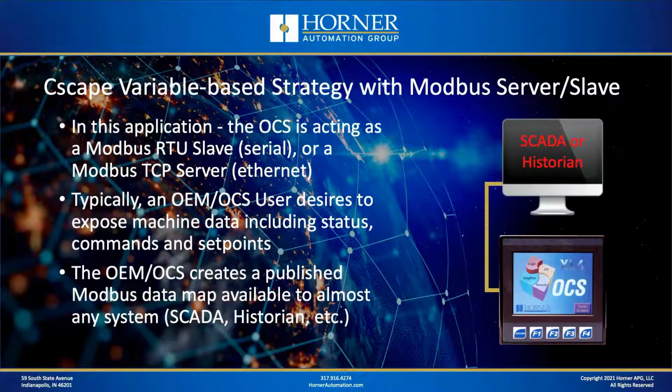So in that scenario, I want to expose some of that data and make it available to those external products, and using Modbus or Modbus TCP is a terrific way to do that, because again, it's the most common protocol, so I can almost be guaranteed that my customer's equipment will interface to it in some way. So really what the job is in this application, as an OEM, is to create a published Modbus data map to make key data of my machine available to the outside world. That's what we're doing here in this first example.